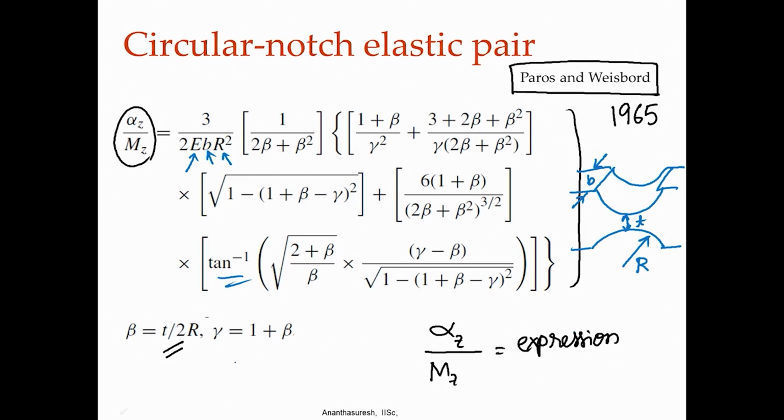the kappa that we want should be relating Mz to kappa here, and the angle in this particular case is shown with alpha z, rotation about the z axis. So, this one is 1 over this expression, the way it is written, okay, very long. While it is easy to put numbers into it and get this kappa value, in terms of design, what thickness T you should have here, what R, what B, it is not that easy here.